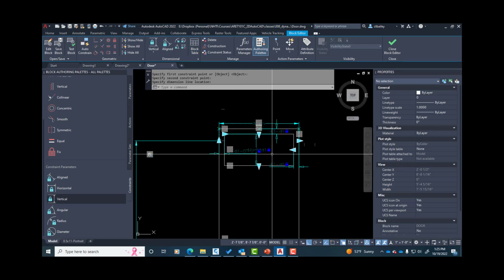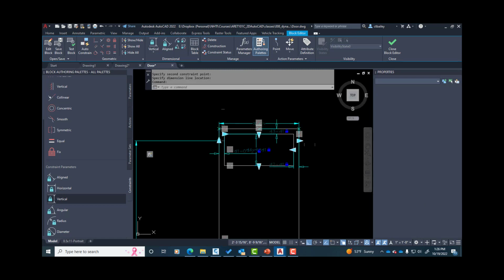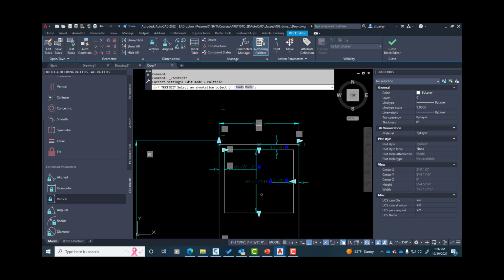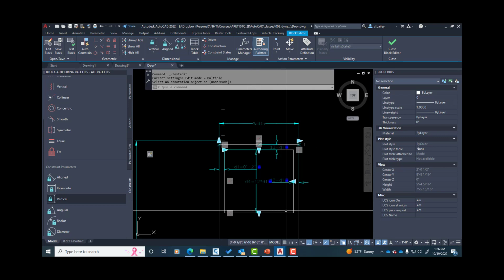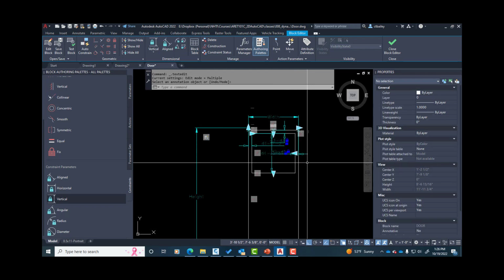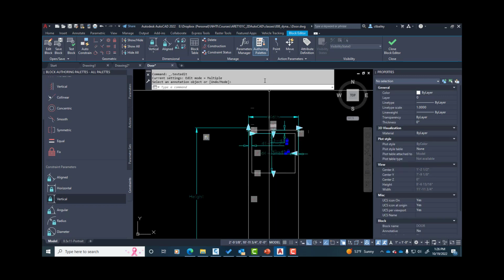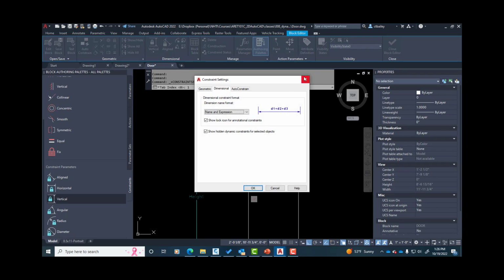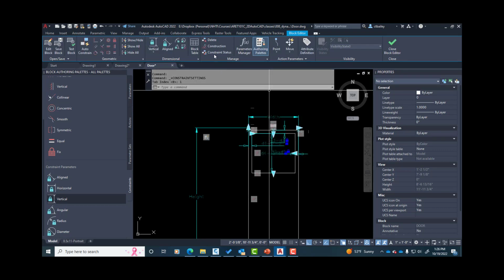6 times is not enough. Let's go ahead and make that 12 times. D4 is equal to 12 times D1, so that's going to be a 24-inch tall window. There we go. Okay, so now I believe for the most part this is a good constraint, and I can clean this up a little bit by knocking these dimensions. Let's see down here.